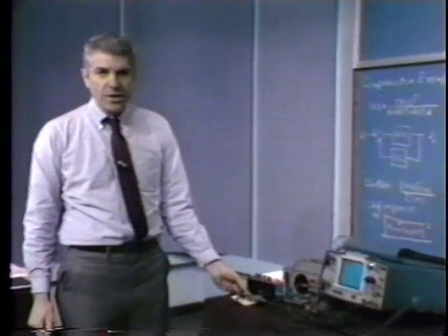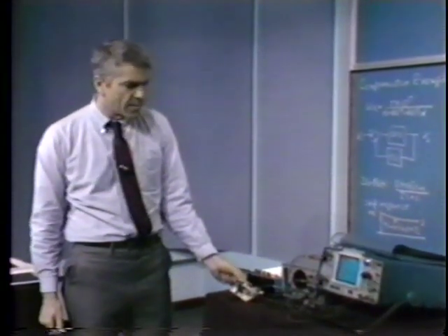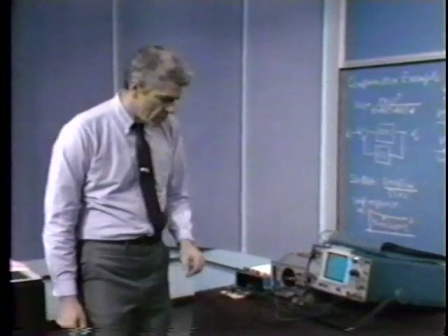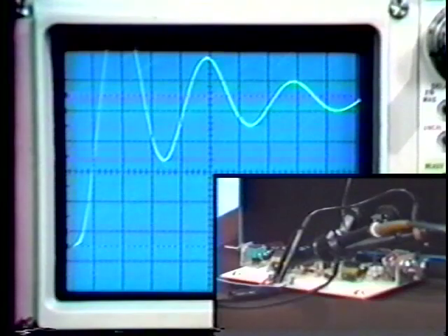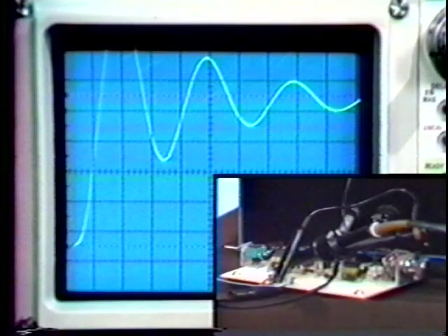While my original statement of the problem didn't allow us to place the lead transfer function in the forward path, our little amplifier here allows us to take some liberties that exceed those in the problem statement. And so let me go back to, first of all, our original uncompensated case, which is this. And now let me look at another point in the amplifier, which will allow me to place the lead network in the forward path. And the hope is that by doing this, we'll be able to get better correspondence between the lead and the lag compensated case.